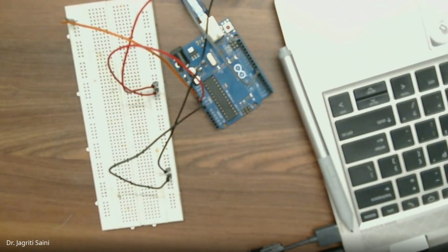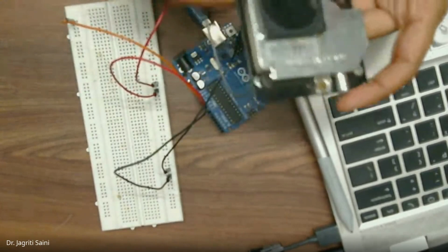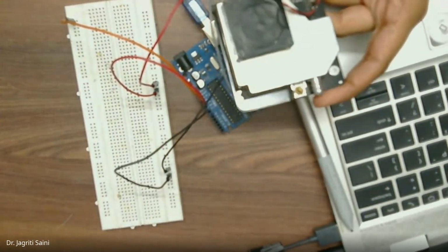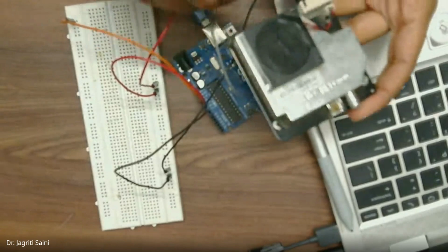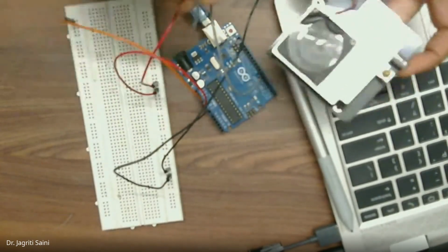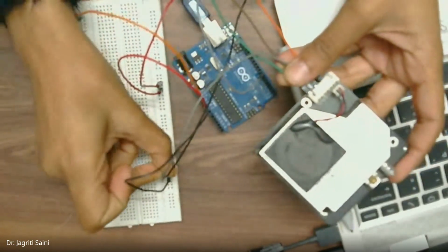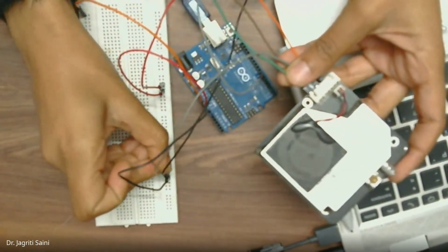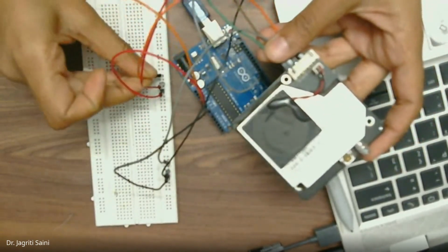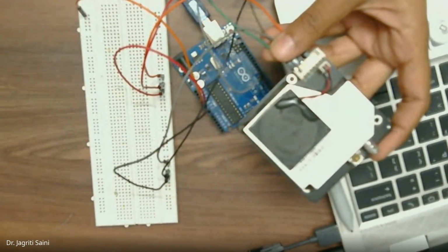After this, I'll be connecting this SDS sensor. As we discussed earlier, it requires UART based communication through transmit and receive lines. So the very first thing I'll do is pick up its ground wire, and I'll be inserting it in the ground section over here. Then I have this VCC. It works on 5 volts. So accordingly, the 5 volt I'm inserting here. Then we have these two.